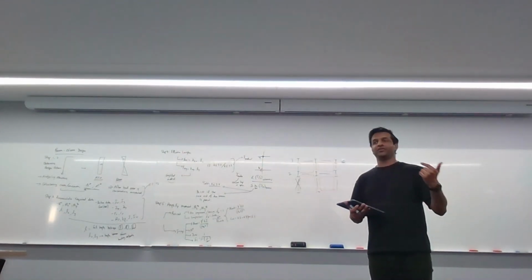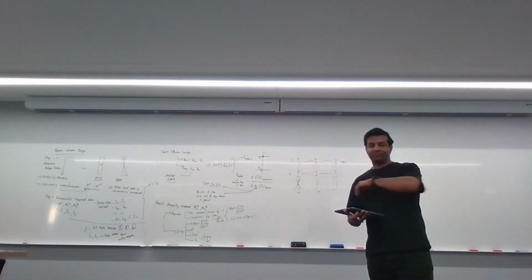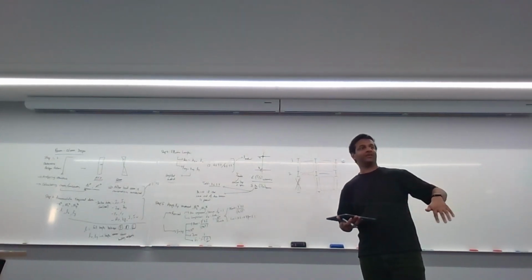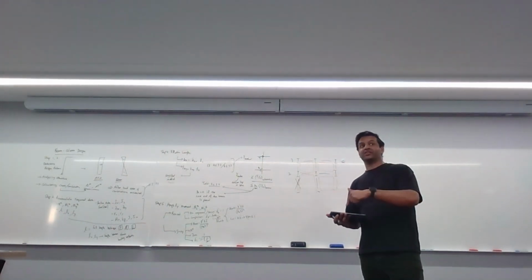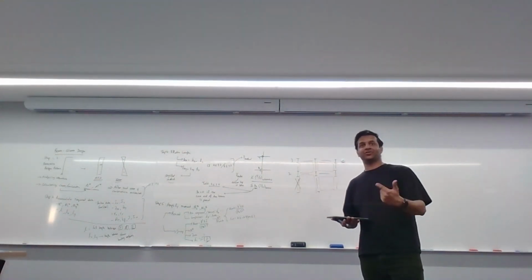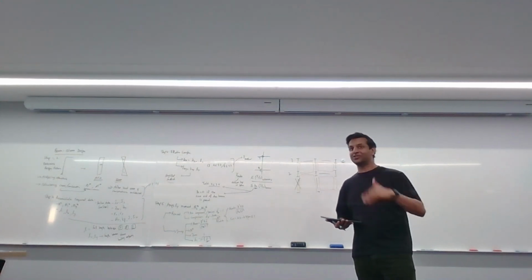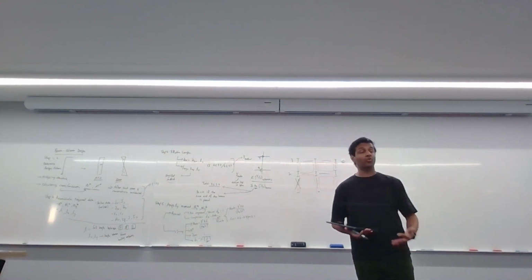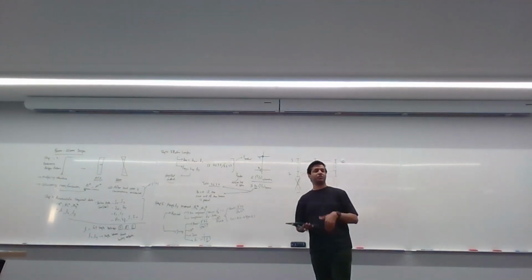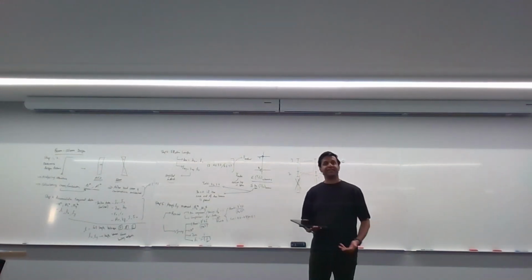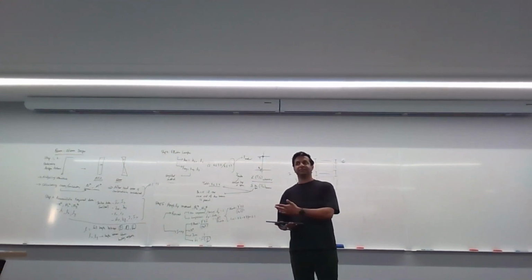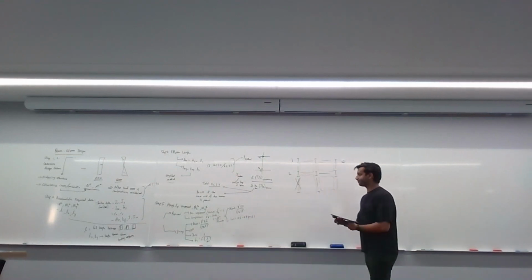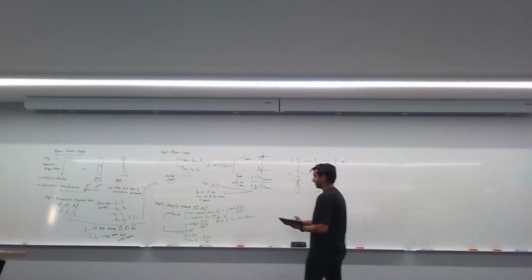If you ever get a question where you're rolling through your calcs and it's super easy, and what you're actually doing is the Y direction is sway and the X direction is braced, just stop yourself and do a sanity check and double check that that's exactly what's happening. You will very rarely see that, because you're missing the point of the brace. Bracing is to strengthen the weaker direction of the column. So if you're only going to brace one side, you'll brace the weak direction. You won't brace the strong direction. Okay, so that's step 5.